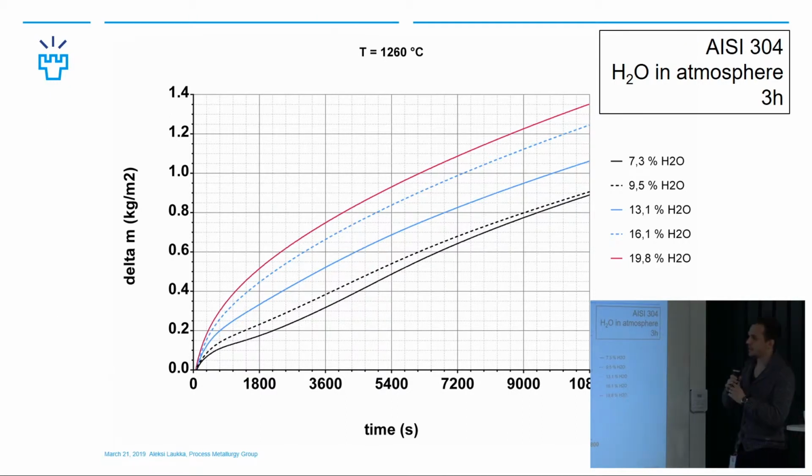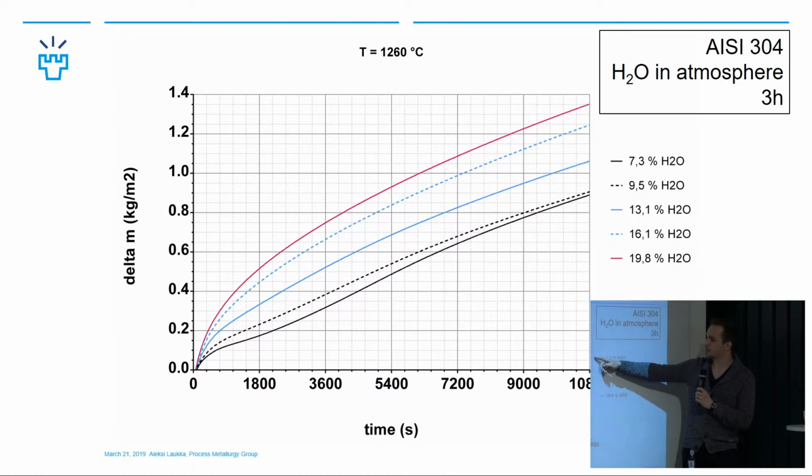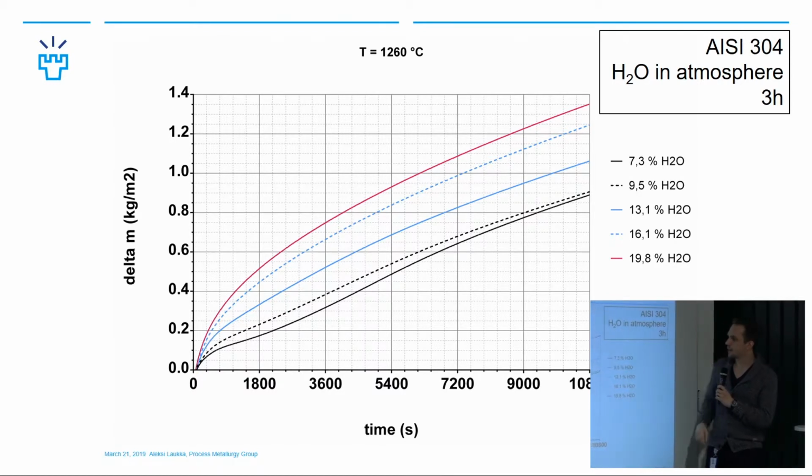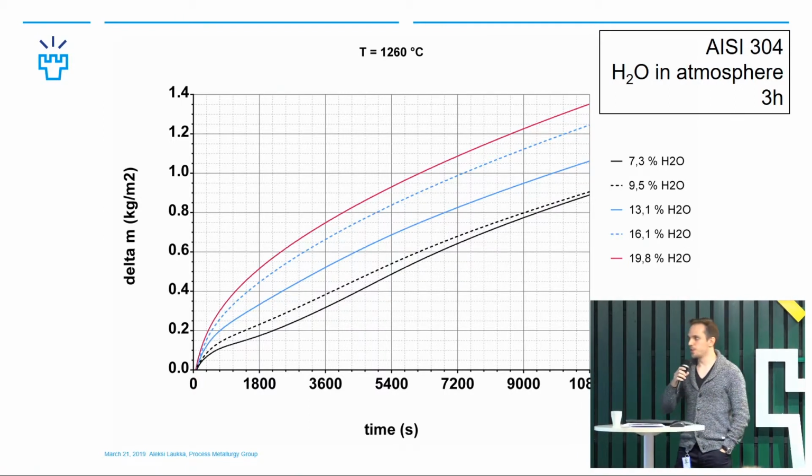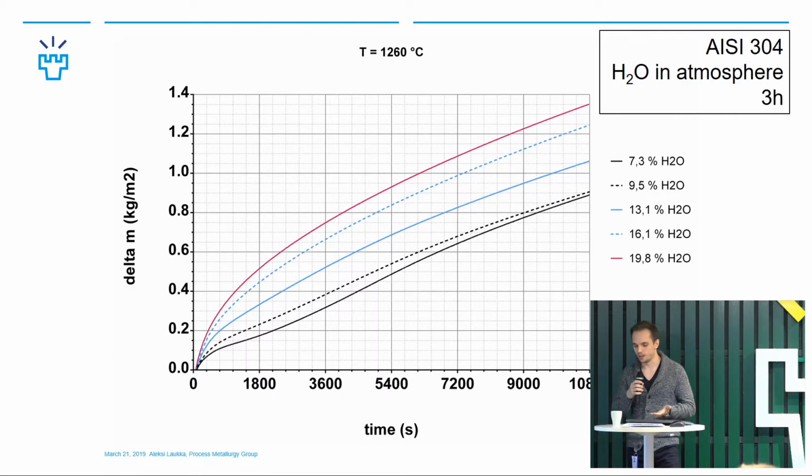And we see that the oxide scaling amount increases slightly by around 20%, but it actually is beneficial because in addition to increasing the scale formation amount, the porosity in the steel or inner oxidation layer and steel interface increases, so the scale removal is easier.